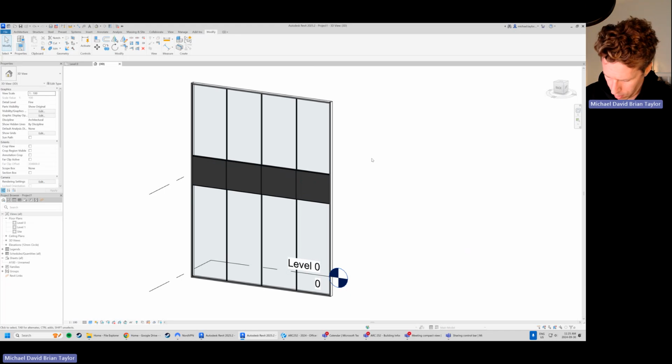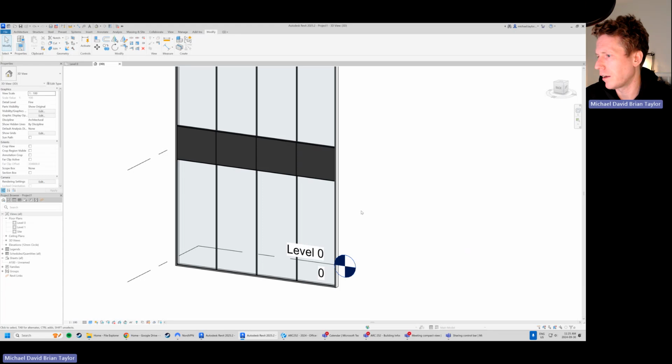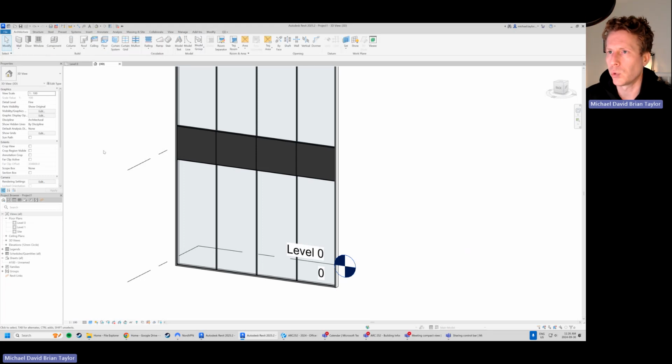Just some more things on the grid itself. Say, for instance, we want to modify some pieces of the grid. What we can do is, this is where the curtain wall grid comes in. And I think that this is probably one of the biggest things in Revit, that it's unclear when you're actually using the curtain wall tool that you need to use the wall tool to start it. And then any modifications you want to make afterwards end up functioning in some additional tools here.